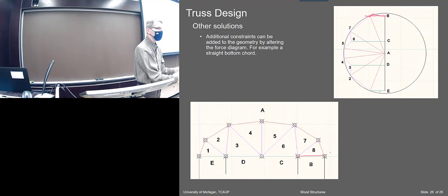To get the weight, you have to actually get the member, right? And that's why I ran this sheet off, just so you don't have to be trying to calculate every member. And there are tables very similar to this. NDS makes a thing they call the manual. Should be on Canvas, I think. I probably posted a copy of it. And they have tables similar to this that are just sort of shortcuts to quickly picking the members.